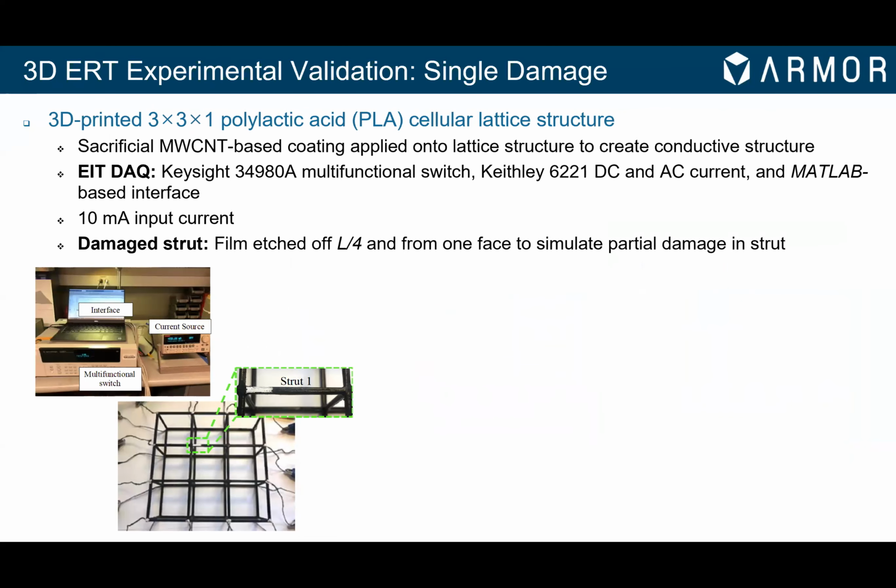Now, once we verified the performance of our 3D ERT method using numerical studies, we then validated this method through some experimental tests. Shown here on the bottom left is our experimental setup, where we have a custom ERT data acquisition system that employs a multifunctional switch with an embedded digital multimeter that is coupled with an AC/DC current source. And all of this is controlled using a MATLAB-based interface. We 3D printed the same